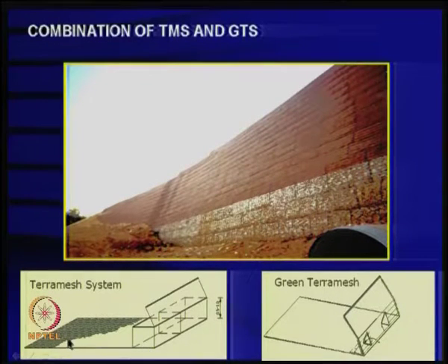This is the reinforcement system, and whatever you can design, you can specify, and then the company may have standard designs. What happens is that when companies have standard designs, our objective as a designer is to cross check the design, because the designs are sometimes not foolproof, and there could be some unusual situations where the designs can go wrong.